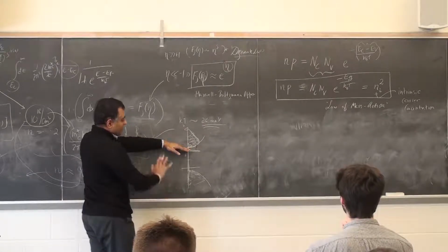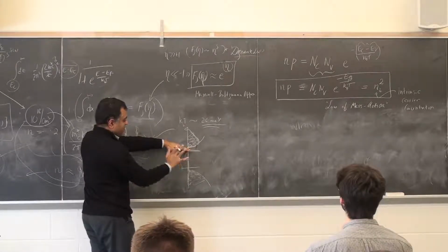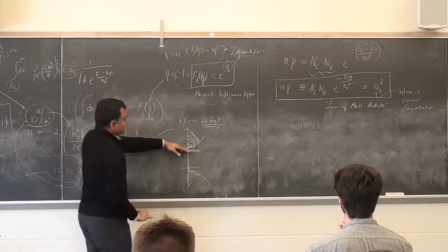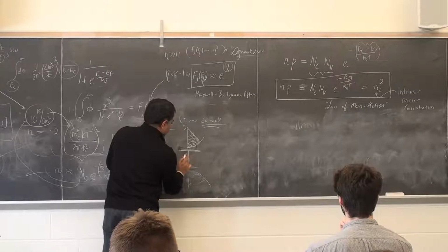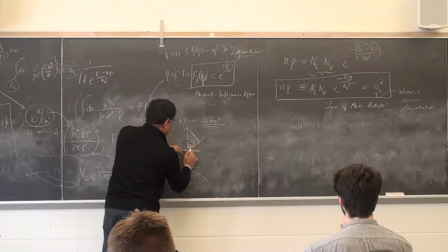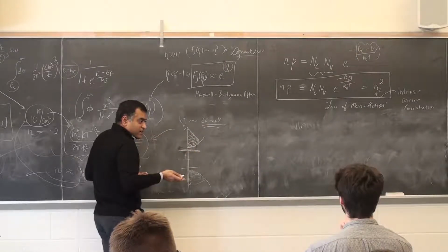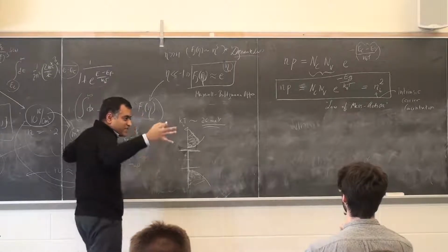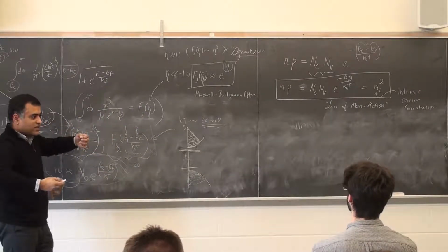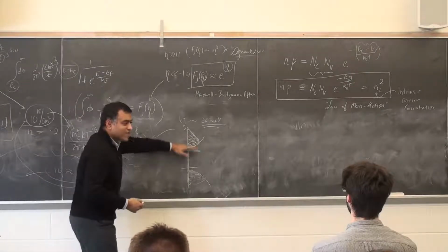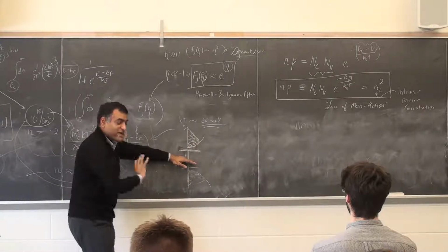Right? More electrons into the system by bringing it from somewhere else. If I do doping, what I'm doing is filling the band with extra atoms that have more electrons than the rest of the atoms. So for example, in silicon, I replace some of the silicon atoms with phosphorus that has one extra electron. So that's how I can move the bands, move the Fermi level. Without it, I can't move the Fermi level.